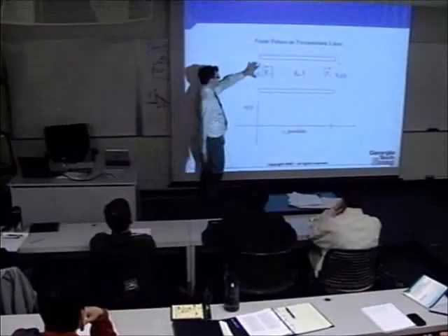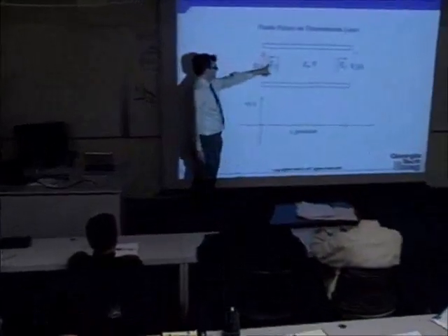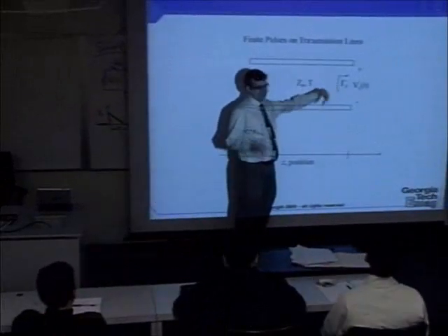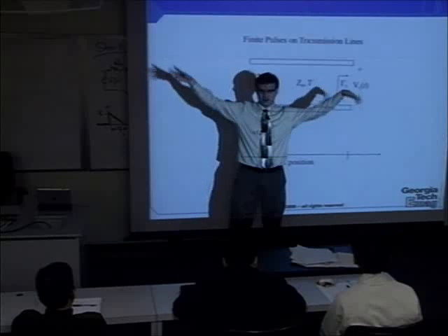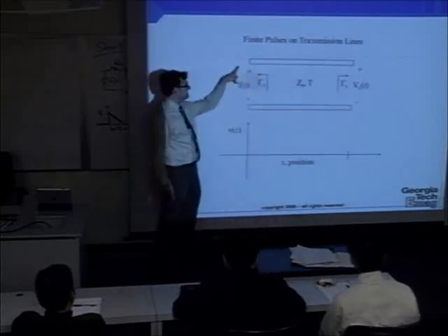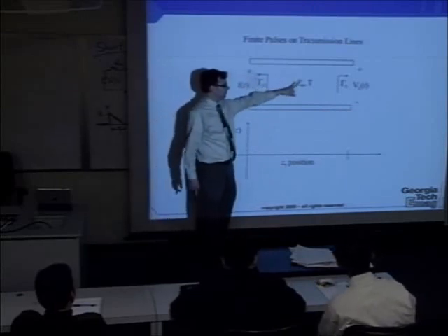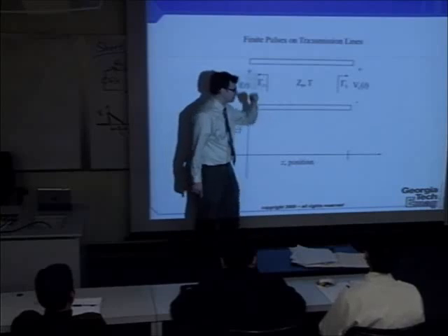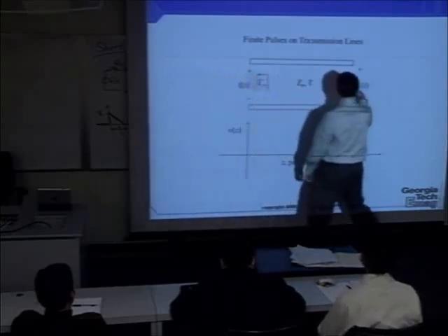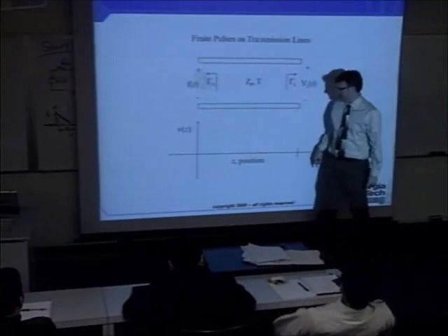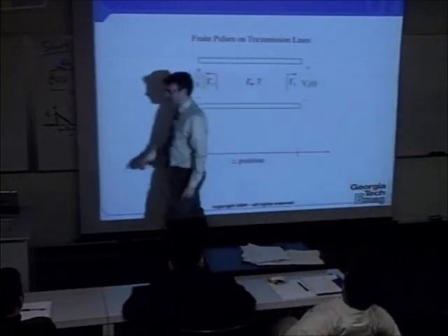We've got a transmission line. I'm going to have a source side reflection coefficient and a load side reflection coefficient. In this example, that's all that I'm going to tell you. I'm not going to tell you all the guts that are connected to either end, but we're going to put a function f of t in as a forward propagating waveform, and we're going to look at the short pulse as it bounces back. And really what I've got graphed here is what the output load voltage looks like in time. And we'll trace that out.